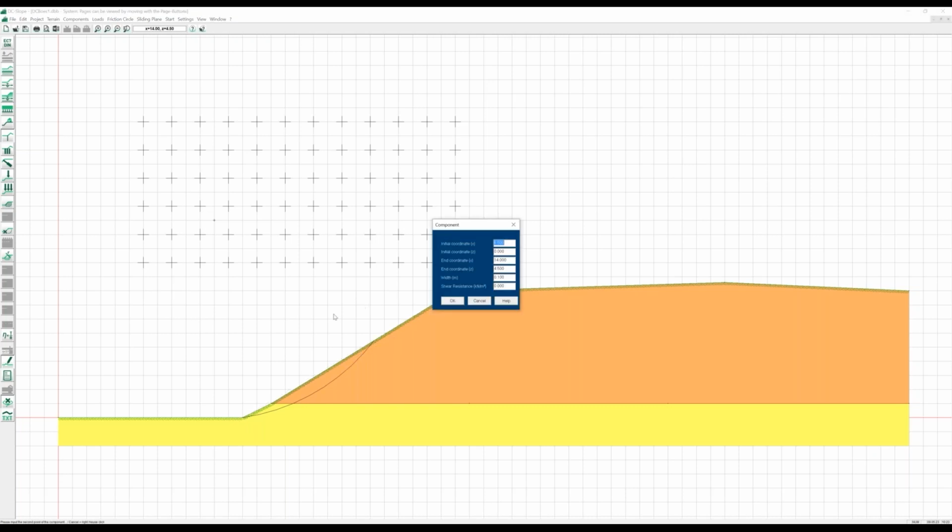So this is covered by shotcrete, and we have a shear resistance of this element, for example, of 500 kilonewtons per square meter, which is about the shear in a non-reinforced concrete. And this element has a width of 10 centimeters and should support the slope here.